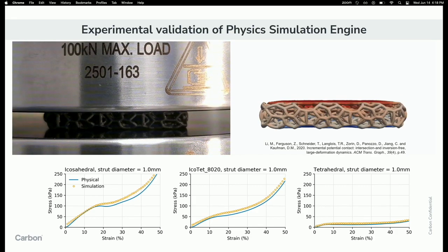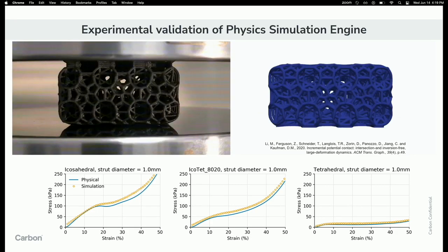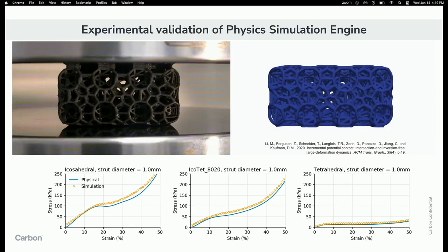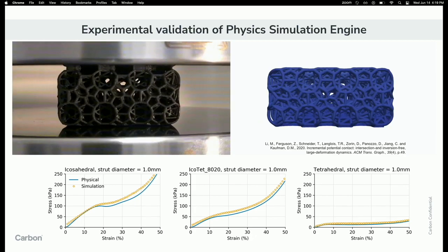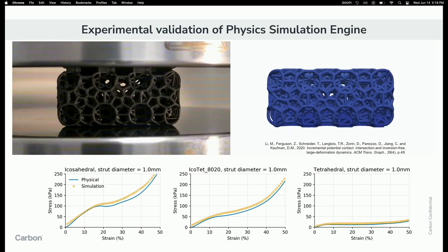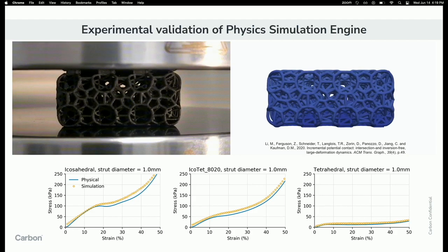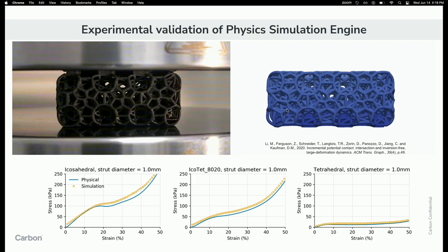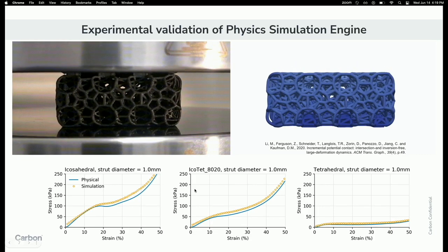It's not commercially available, and for this I have to give Daniel A. and group a huge shout out. There's an algorithm called incremental potential contact, which was developed at NYU, and we started working with them. We've been working with them for the past 2-3 years. For FEA nerds, this is an implicit solver. The time step does not go down exponentially as the buckling and the contact happens. Once we figured out how to make it work, there were some parameter tunings, but tuning is done, it's in the box. These simulations can run for different lattice topologies without any human in the loop.